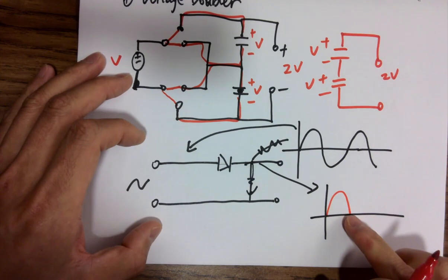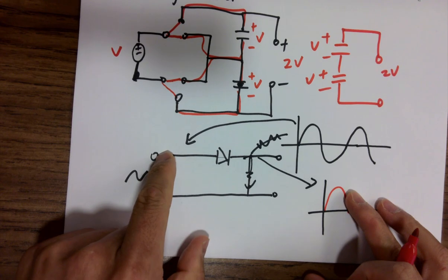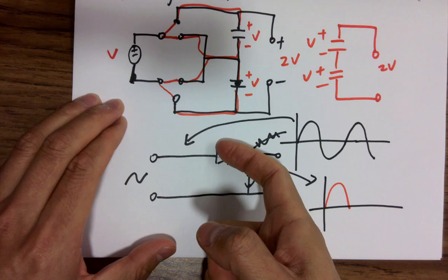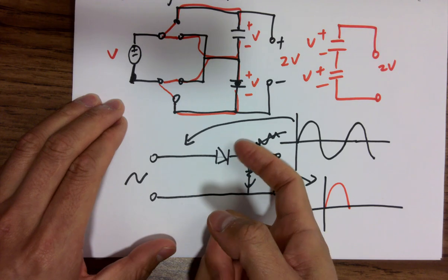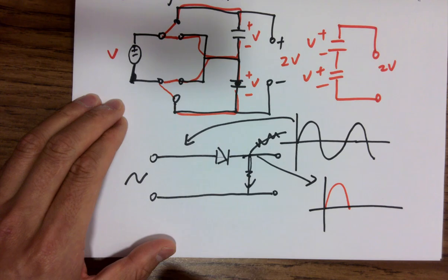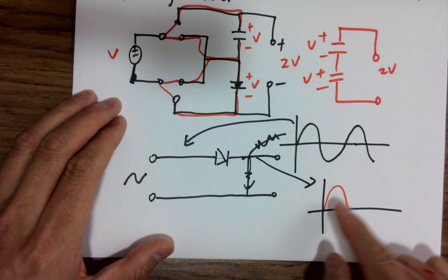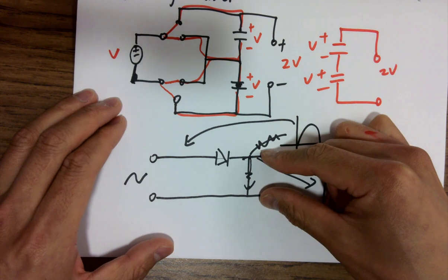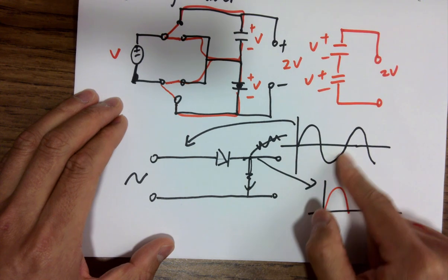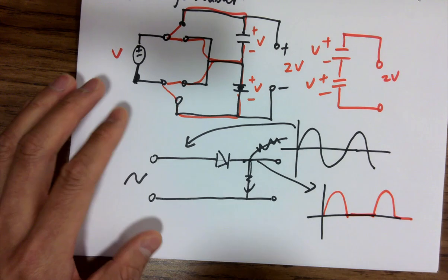But whenever it reaches 0 and starts getting negative, the voltage here will be higher than the voltage here. So it's trying to push current backwards. But is it able to push current backwards? No. So that means there's no current. No current means what? No voltage drop. So it means these two voltages will be the same. If I'm measuring the output as the voltage difference between the two nodes, what would the voltage be during that cycle, whenever it's negative? 0 volts, right? It will be this. Okay?